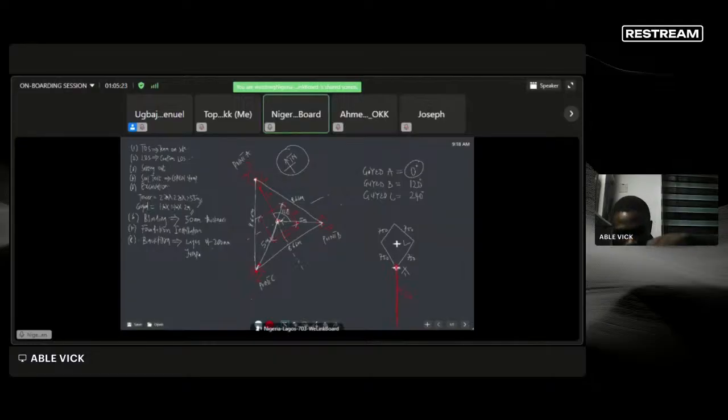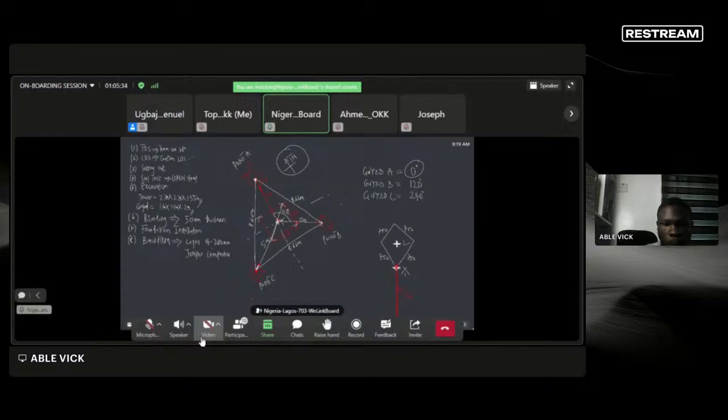And you'll be using a jumper compactor for your compaction, in layers of 200 mm. That's the backfilling requirement. So it means for your tower foundation, your tower foundation is like this.